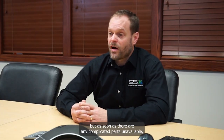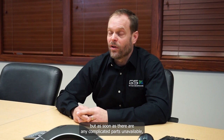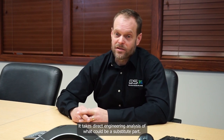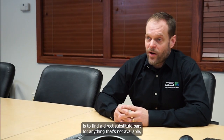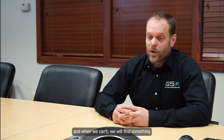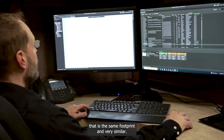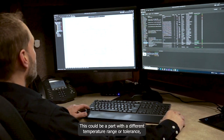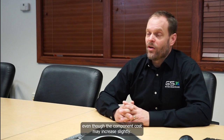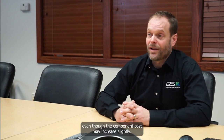But as soon as there are any complicated parts unavailable, it takes direct engineering analysis of what could be a substitute part. Of course, the primary goal is to find a direct substitute part for anything that's not available. And when we can't, we will find something that is the same footprint and very similar. This could be a part with a different temperature range or a different tolerance, but it lets us continue building with the same printed wiring board, even though the component cost may increase slightly.